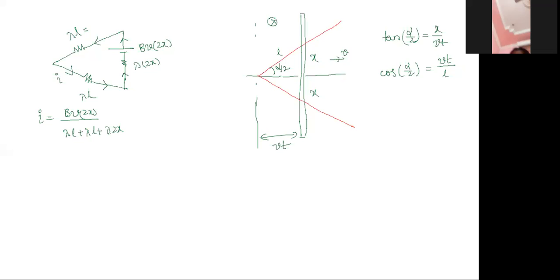So the inductor behaves like a source now. This is the current I which is increasing, so the induced current is in the opposite direction, I induced. It wants to decrease the current. Similarly, if I is decreasing, it behaves like a source. Once again the magnitude is L dI by dt at that instant, and the induced current aids the current. It wants to add to the already existing current.